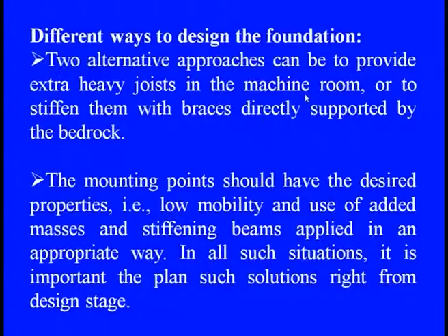The mounting point should have the desired properties when we are doing this. First, low mobility, because if high mobility is there, then it is not a good isolator. And along with this low mobility, added masses or stiffening beams can be applied in the appropriate way according to the application.